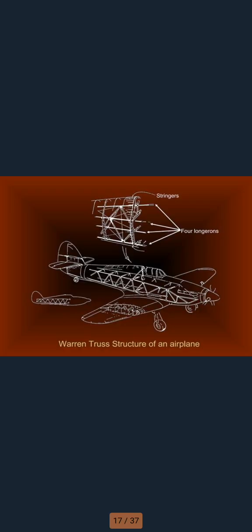Forces on airframes: aircraft structures must endure high mechanical stress during flight and ground operation. Tension: pulling force that stresses the metal. Compression: squeezing force that crushes the metal. Shear: opposite forces sliding across the metal. Bending: a combination of tension on one side and compression on the other. Torsion: twisting force.